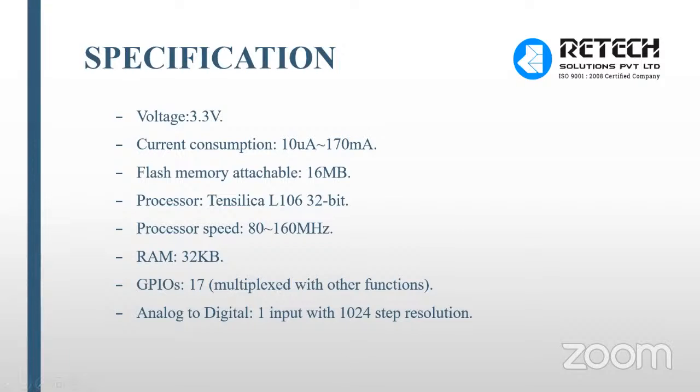It has a Tensilica L106 32-bit processor, so this is a 32-bit microcontroller. The working speed is 80 to 160 megahertz. The RAM is 32 KB.